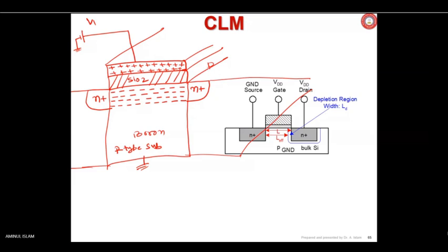Okay. So by heavy ion implantation of the p-type material with n-type, pentavalent material, you have made it an n plus region, and from the top you give the connection.